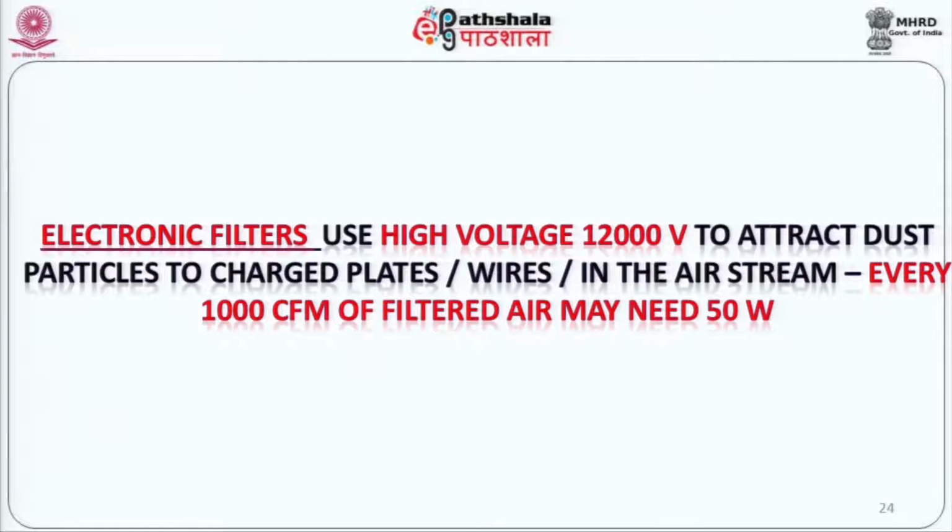Now, apart from these dry and viscous filters, one can look at electronic filters. These electronic filters use power, use electricity. They charge multiple wires across an air opening to very high voltages with the help of capacitors, and this high voltage is used to collect dust. It is like the small tricks that we used to play as children. You used to take an ebonite pen, rub it on your hair, develop static electricity and pick up a small bit of dust from the table.